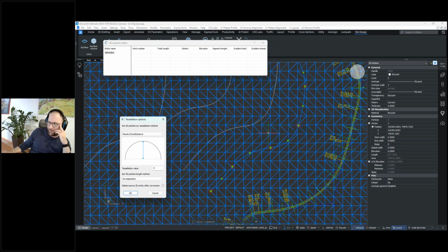And as you know, we don't have any arcs in 3D, so arcs are only possible to draw in a 2D plane. So we need to segment those arcs for the 3D polylines. We can do this using this command here. So we actually define the distance between the arc and the 3D polyline.